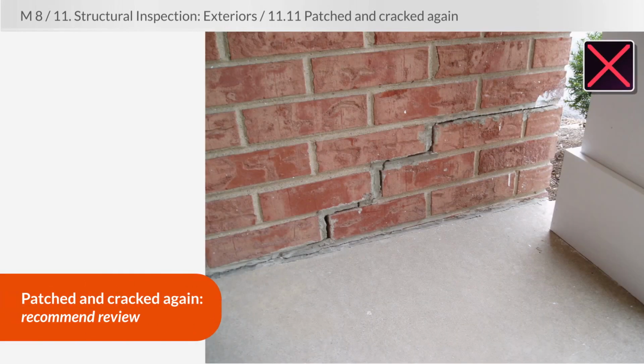This has been patched and it cracked again. This crack will also show up around the corner. Most likely, the foundation is moving, so recommend further review by either a foundation contractor or, if you really feel like you need it, a structural engineer.